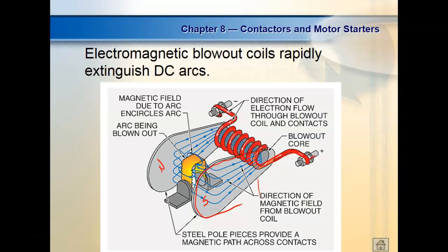AC, though, is a lot cheaper because with DC, we have to provide current to the rotor rotational portion, while with AC, we induce it in there. So AC motors are a lot cheaper per horsepower. But once they came up with those variable speed AC drives, they're still not as good, but they want to create a constant torque. But AC motors are so much cheaper. So now AC motors are dominating your speed control circuits because of the cost.